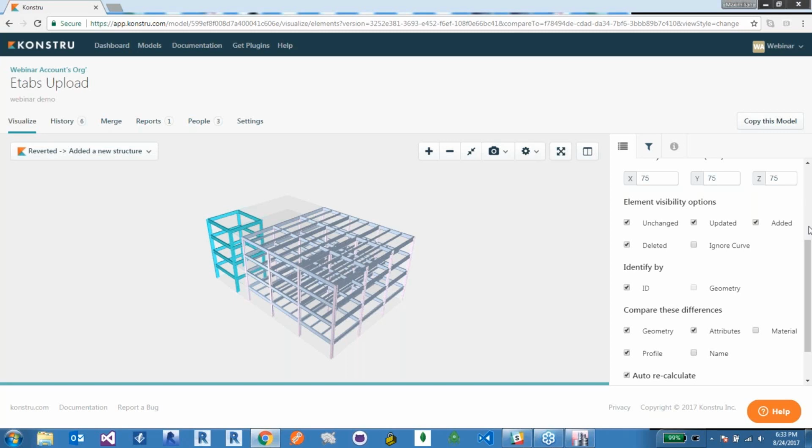The only thing that could happen is if you would, for example, download your Revit model into two different Revits. Let's say you have an empty Revit file on one computer and an empty Revit file on the other computer, and you would download the model into both of them. The Revit IDs would always be set to the latest one you downloaded to. So in this case, they wouldn't be the same anymore. So if you work with multiple Revit instances, make sure you also work with a central model, because then this wouldn't happen at all.